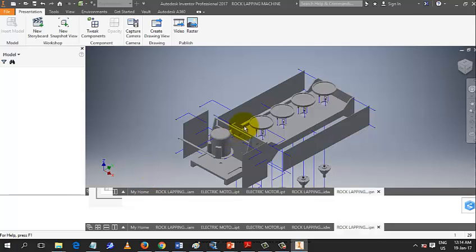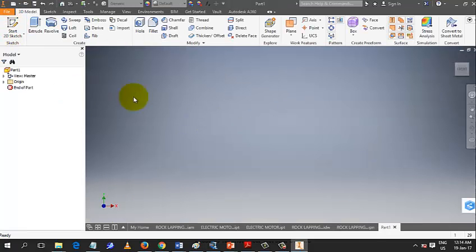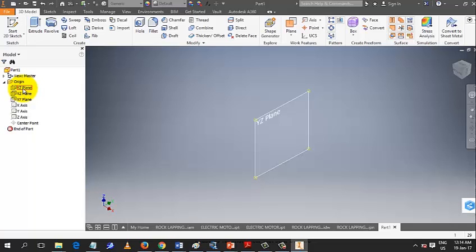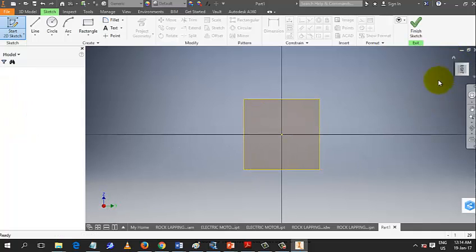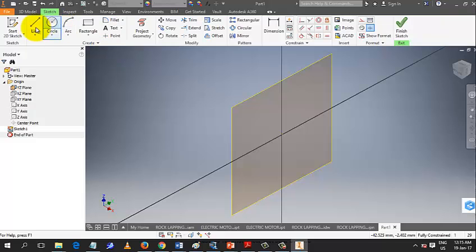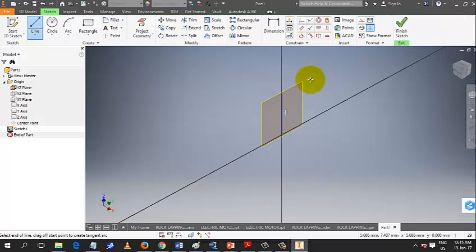Okay, I think I've just created a new one. I just click on this new button. Okay, and I have this. All right. Okay, let's create the origin. Let me create it on this plane. I will have to make it visible. Then let's go to sketch. Let's start a sketch on this plane. I want an isometric view. Then let me say we are creating something like this. This is just a demonstration, not following a particular dimension.